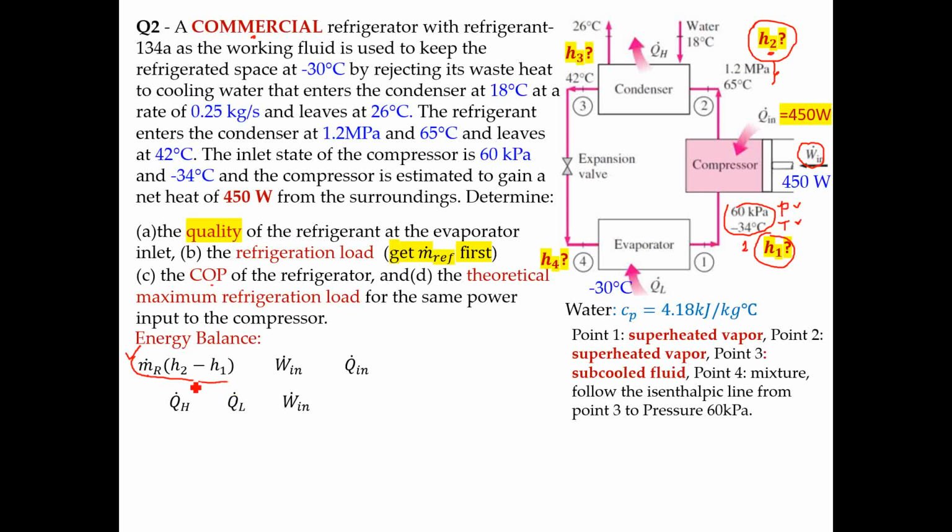So that's the amount of heat transfer throughout the compressor. What's the relationship between this amount of heat, W, and the heat generated by the compressor? I hope you have a think about that. What's the relationship between them? So if I say this amount of heat would be equal to the work input plus the amount of heat generated by the compressor, would you all agree with that?